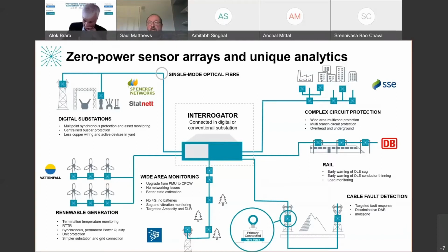So we're discovering in the UK that a lot of large-scale wind farms have export cable and array cables under the ocean, which are failing prematurely. They should be lasting 25 to 30 years, and they're only lasting 10 to 12 years. And a lot of that is because of the variable load and the electrical stress that they're being subjected to from these generators. And these inverters are causing a lot of problems.